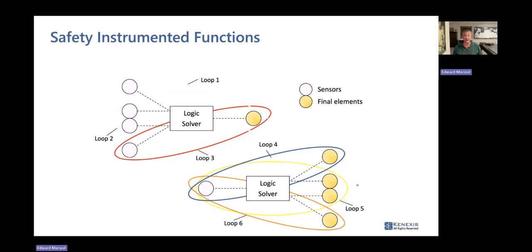Okay, you're bringing up a very interesting and very complex topic that occurs all the time in my day-to-day work. I know that I've discussed this with someone this week. So when you're looking at this kind of overlap, this sensor right now is going to be used in 3 different loops. Is that okay? Is that not okay? Do I need to somehow mathematically account for the commonality of this sensor in these 3 different loops?